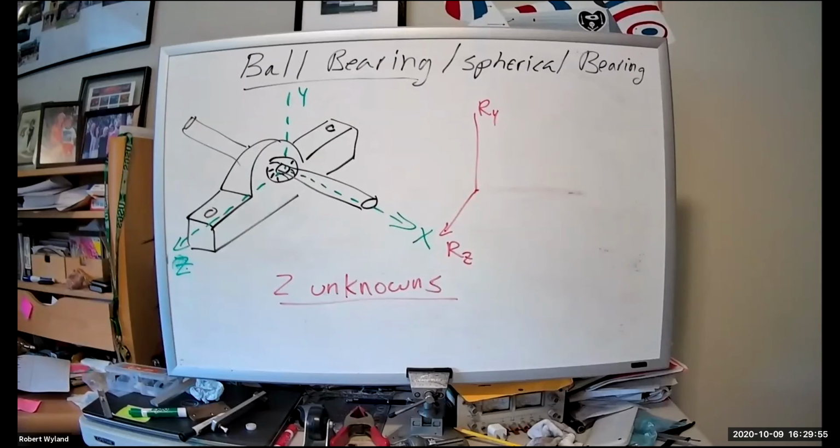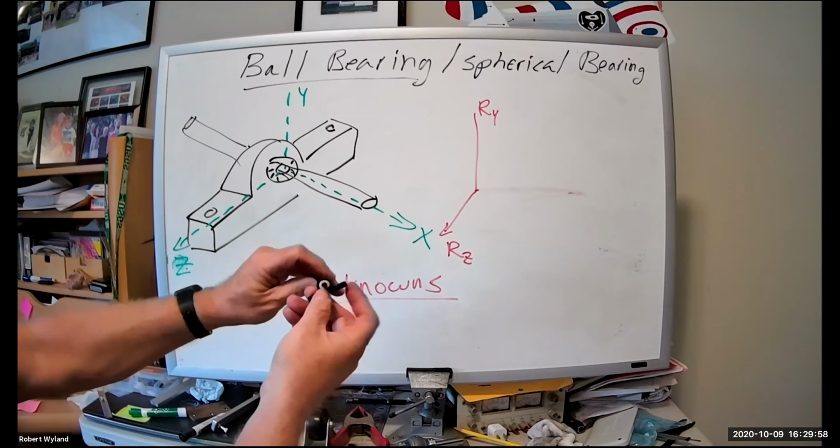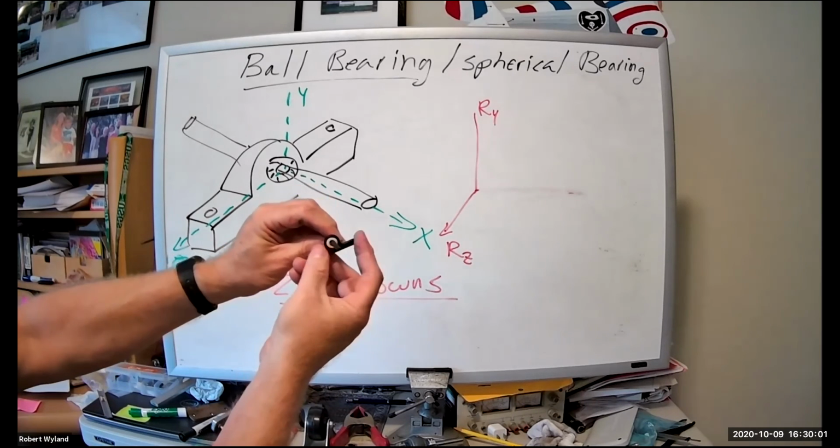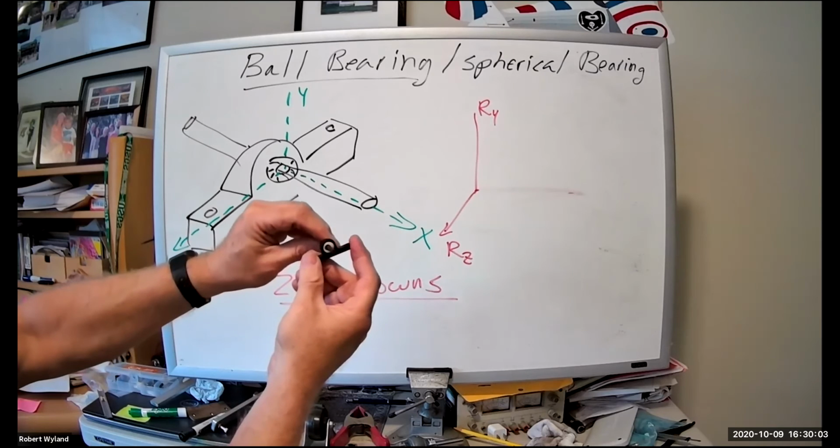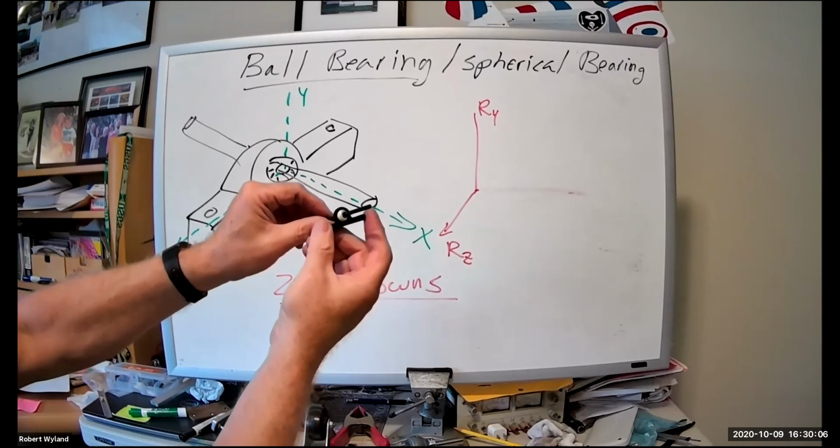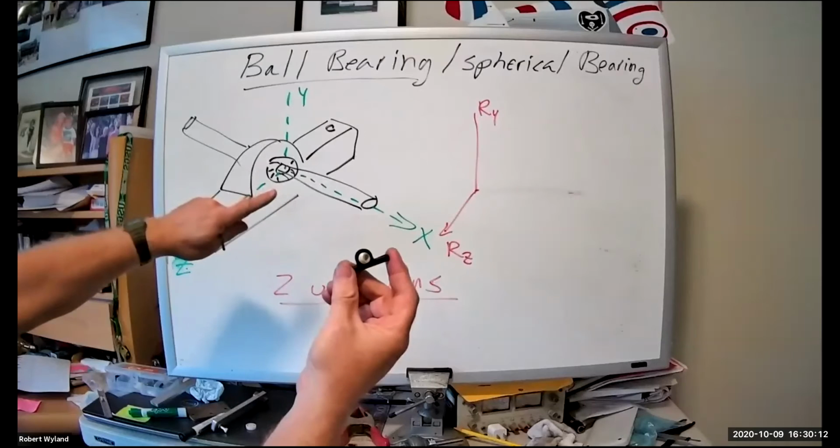Hey, Rob. Just because someone else mentioned it earlier, it allows moments to freely move, but obviously up to a point. As long as, we just assume that it moves freely within a certain range, kind of thing. Correct. Yeah. And you will try and design your part so that you're in the middle of your range to start with. You wouldn't purposely design it off at an angle like that to start with. Particularly if you were trying to put your next pillow block down here.